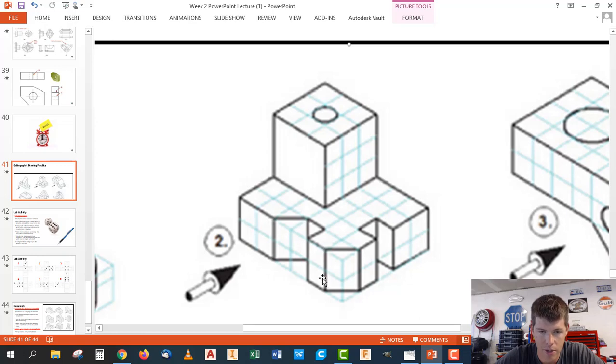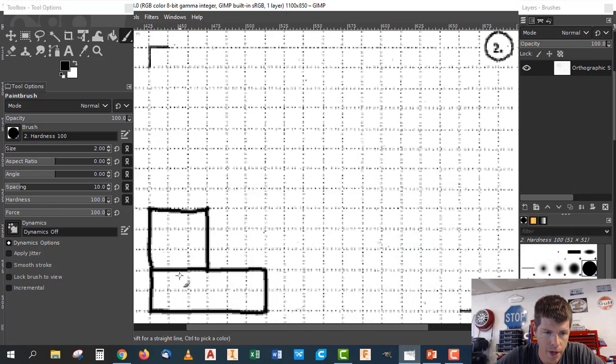Another box, we have an edge. So basically, we're going to go over 2 lines, and then every box we're going to put a line because of all these individual things we've got going on. So let's go over 2 boxes. We've got an edge there, an edge here, an edge here, an edge here. Okay, we got all this stuff going on. I think that finishes our visible lines for that front view.